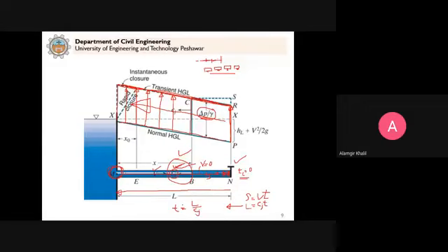It means this much time is taken by the wave to reach from point N to point M. And if this wave is going to return back to the valve, then how much time will it take? This is the round trip, denoted by TR in your textbook. It means the pressure wave generated here goes to the reservoir and then comes back, so it will be 2 times of this. So this will be equal to 2 times of that time, clear?